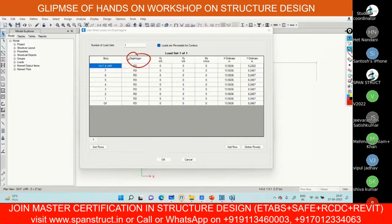So how much you want to apply at the OHT level, terrace level, 6th floor, 5th floor, 4th, 3, 2, 1, ground floor: Fx value, Fy value, and Mz value. You have to calculate all these values in the Excel sheet and apply them. So this is not automatic, you have to calculate it and apply it.